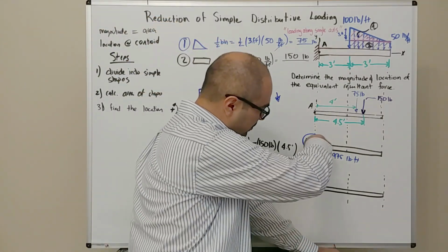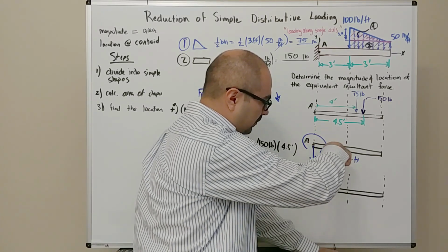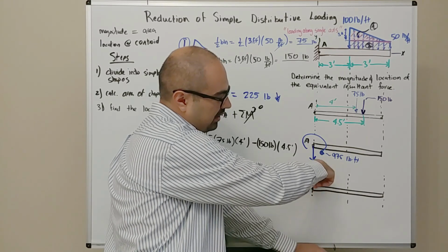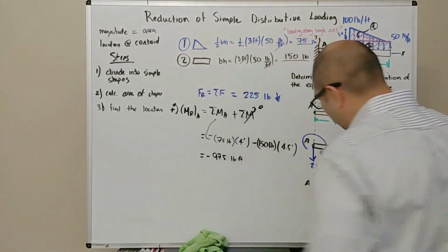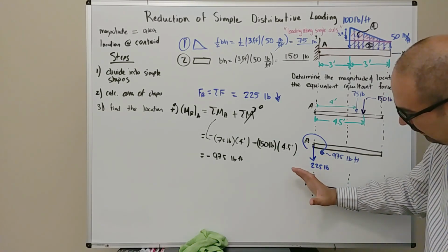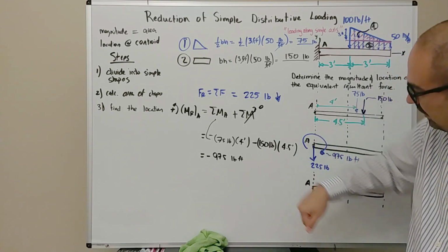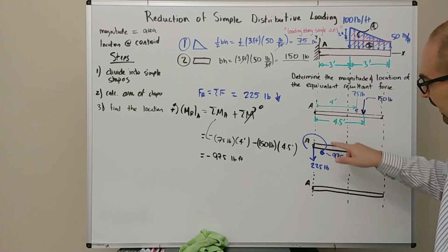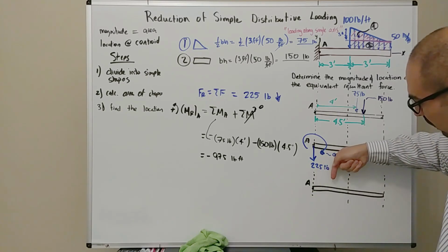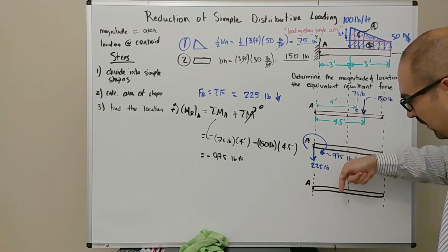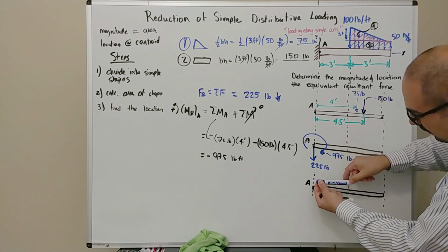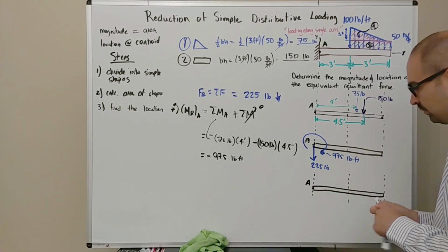So the question is going to be, first, which direction should I move this resultant force? If I go this way, not only is it off the body, but if the force is here to our left and is pushing down, it's going to create a positive rotation. Here we want a negative or a clockwise rotation. So it makes sense that I need to move this force down here to the right so that when it pivots at point A, and if I push down, it'll rotate clockwise.